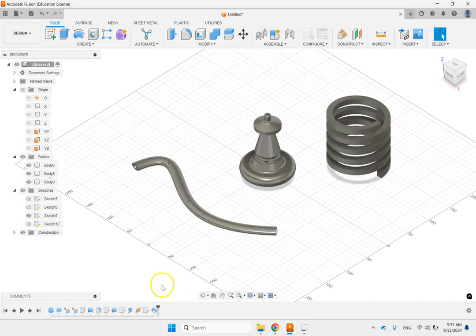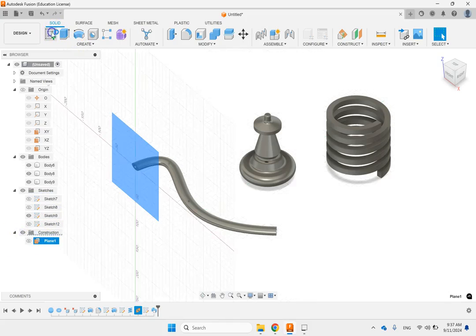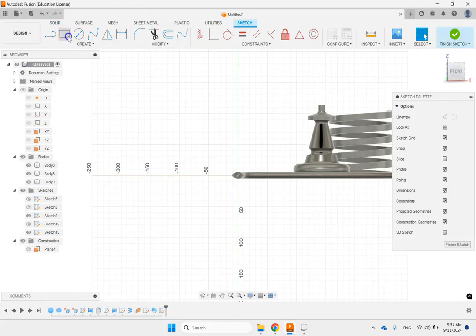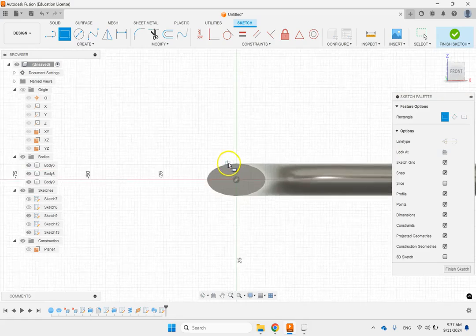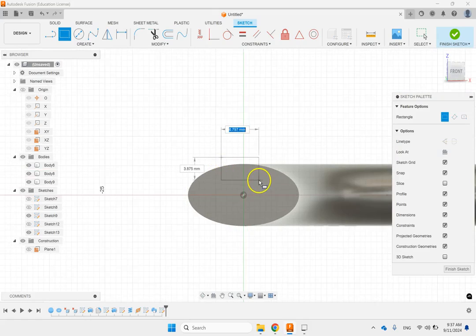So this is sweep and cut sweep. And let me very fast do a cut sweep as well. So I'm gonna go to this new plane, and I'm gonna draw another sketch, and this time maybe a corner rectangle. And I want to cut through this object, make something like a keyway or a slot.